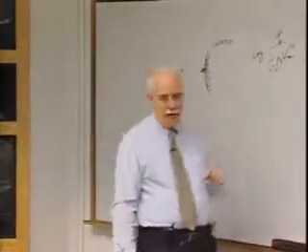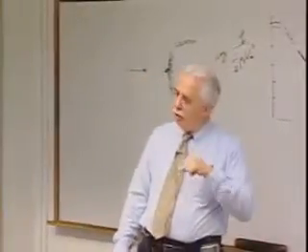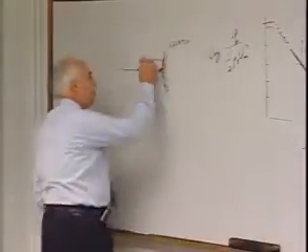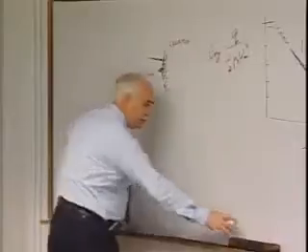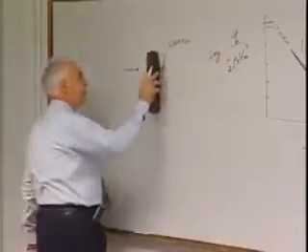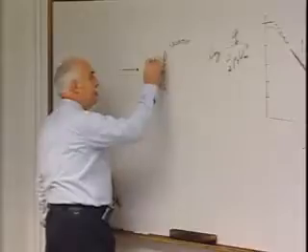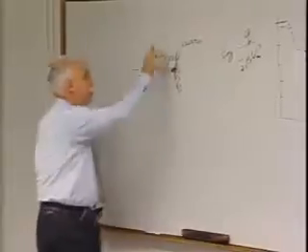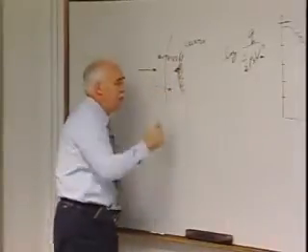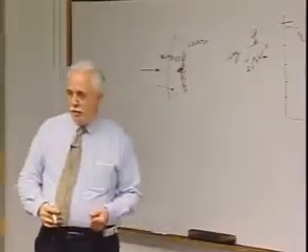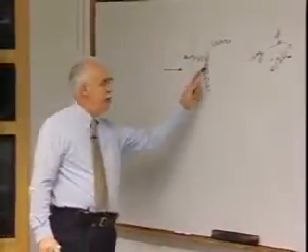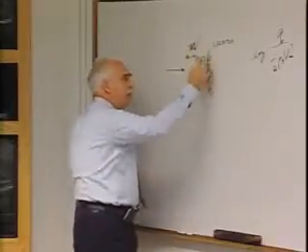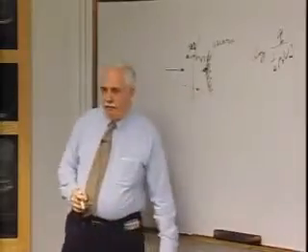But a far more effective way of getting rid of that heat for us in manned space flight at the higher altitudes was to re-radiate it. How do you draw re-radiation there? I guess sort of a wavy line. Radiation is always a wave, right? And so first order, 98% of this energy goes into heating the air, which flows around the vehicle. The other 2% that gets to the vehicle, George re-radiated 98% away with a high emissivity, high temperature surface.